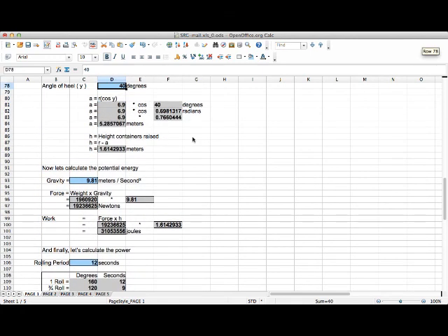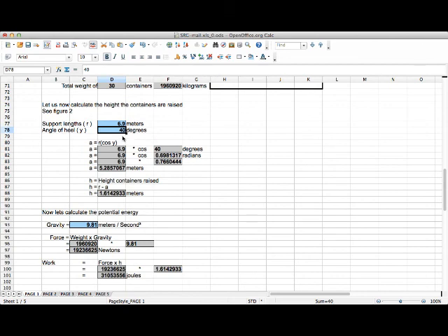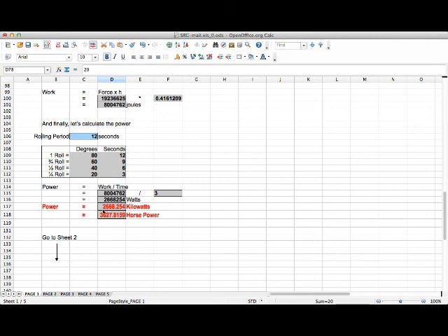Okay, a lot of people would say that 40 degrees is too much. And I could only achieve this 40 degrees here if the ship were to synchronize with the waves very well, and the waves were very constant too. So let's reduce that. Let's try and be a little bit more realistic here. So now the ship is rolling 20 degrees, and let's see how much energy that gives. Well, that's a lot less energy, isn't it? Now we're only producing a little bit more than a wind turbine at 2.6, 2.7 megawatts, much less.